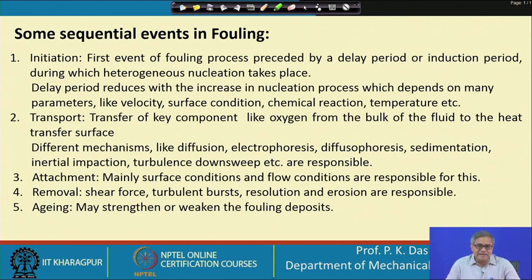That is getting separated out and deposited on the heat transfer surface; that is fouling. So, again let me tell you that generation of a new species, or separation of a species from the circulating fluid stream and its deposition on the heat transfer surface, is fouling.